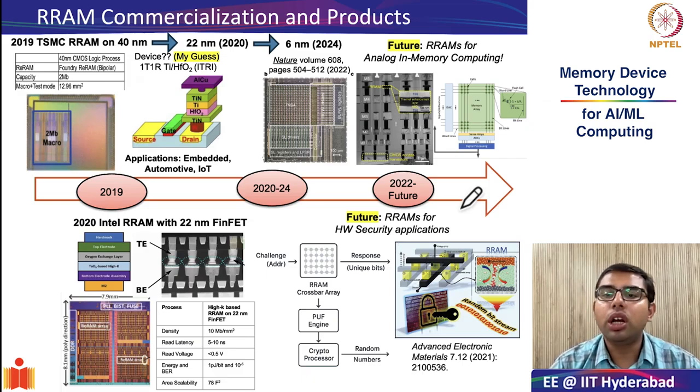In the case of retention, the thermal dissolution of conductive filaments in the low resistance state and diffusion of ionic species in the high resistance state were both causing a drift in resistance in these respective states as a function of time. Also, we looked at how having gradual IV characteristics can enable multi-bit operation with DC biasing, and furthermore, using very short pulses of hundreds of nanoseconds, you can gain access to multiple non-volatile resistance states.